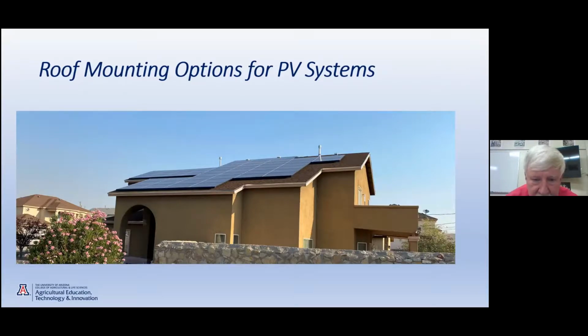And you can see that they've used quite a bit of their roof area. They basically filled up the roof as much as they can with solar modules. And so what you're looking at is the size of your roof, how much you can afford, how much you're trying to maybe offset. Maybe this particular house, they're going to offset 100% of their electrical demand, and so they have a very large system. Some communities have restrictions on the placement of your solar modules. For example, I know in California, they have a restriction that you have to maintain a 3-foot spacing all the way around the modules, around the entire part of your roof.